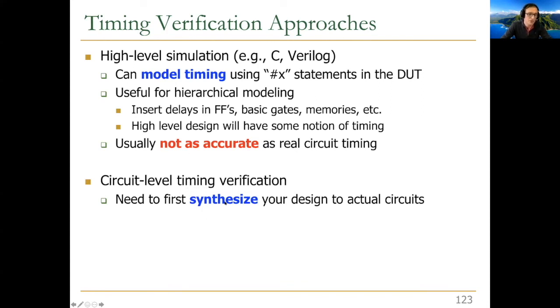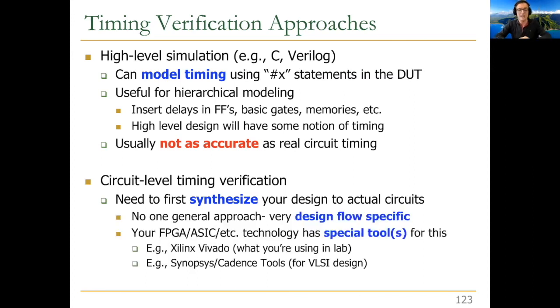For this, you need to first synthesize your design to actual circuits. Basically, you have to go through high-level synthesis or whatever you do to actually create an actual circuit into your FPGA or ASIC, etc., or some low-level design netlist, let's say. And there's no one general approach over here. It's very design flow specific. Your FPGA or ASIC technology may have special tools for this. Usually they do. Like Vivado has some tools for this, assuming some backend that you compile into.